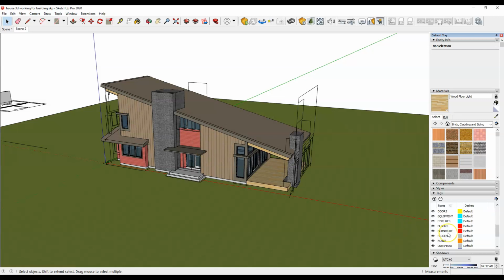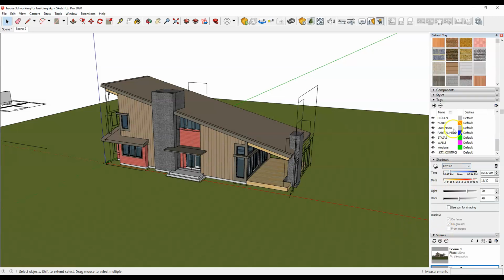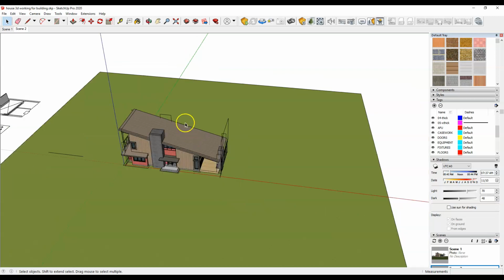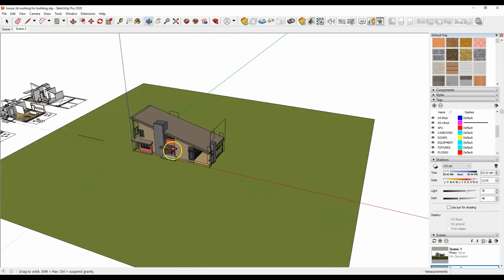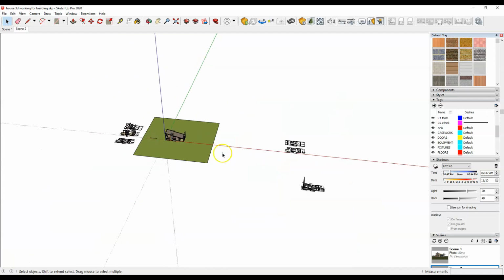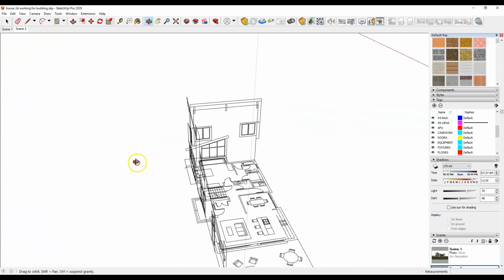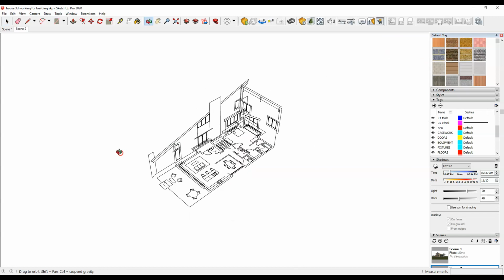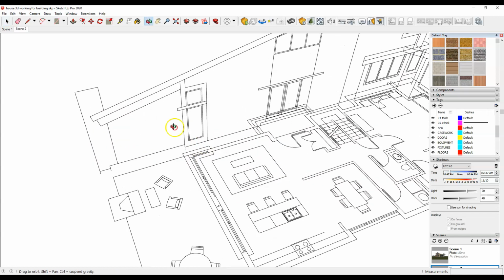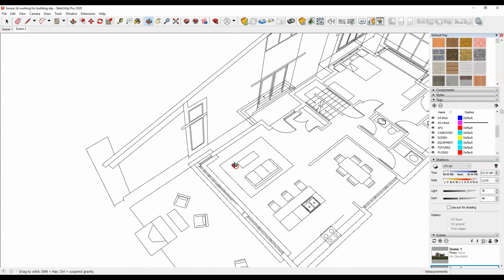These other layers in here, just so you know, are actually all from the CAD layers. Those get imported when I imported the CAD. You don't need to worry about those. They can stay as is, but that's why those other layers are there. So things are in groups. Always draw on untagged, meaning don't use the layer control for the most part. So anyway, you get the scaffolding up, and I'm going to go back to this raw modeling. So those are the first two key rules. The next thing I want to mention is how to go about modeling a house like this.